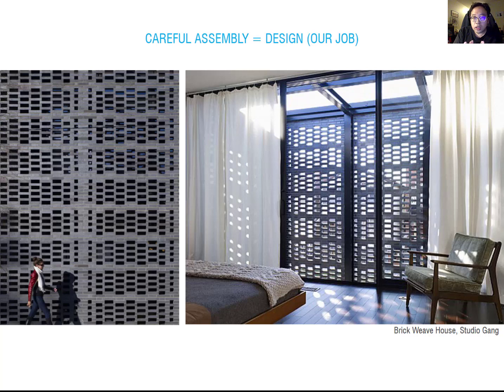So this brick design is actually supported by the metal structure here. You can see this is a metal structure, and the brick only works as decoration. So nowadays brick is not an actual structural material. It is more used for decoration purposes. That's why it is possible to make these types of facade design. So we will talk about this decoration purpose of the material, and also the structural purpose of masonry, later in this lecture.